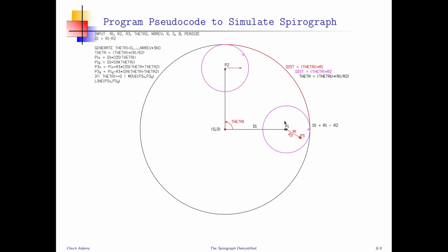Now when you put the disk inside here and move it against the edge here, the hole that you pick is not necessarily in line with P1 through the horizon. So it starts with some angle offset, call it theta 2. That's the original offset. You could take the disk out, rotate it enough, and then get it where P3 is on this line. You see what I'm talking about? I need that. I'll just input that offset into the program.